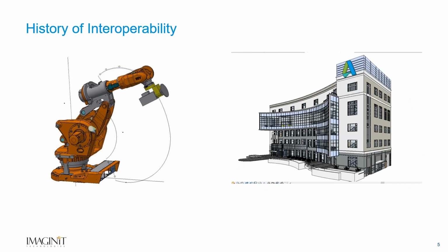Then we got here. So there's two very different modeling kernels that we're dealing with. And I'll talk about Inventor just for a moment. Inventor is a purpose-built tool for mechanical design. When I'm working in Inventor, I'm working in terms of individual components being put together into assemblies, creating detailed drawings of those. Ultimately, I end up with a complete 3D model that should be a digital twin of its real-world counterpart. So a lot of times I'm worried about nuts, bolts, screws, getting hole sizes down to the thousandths, some of those ideas. And it uses a specific modeling engine to do that.